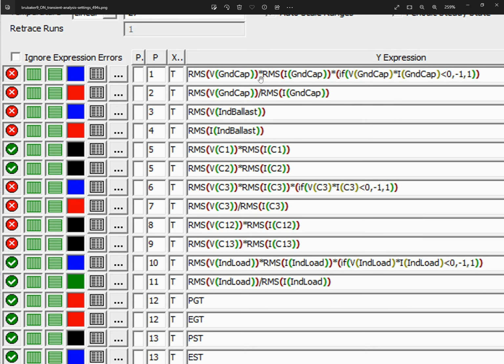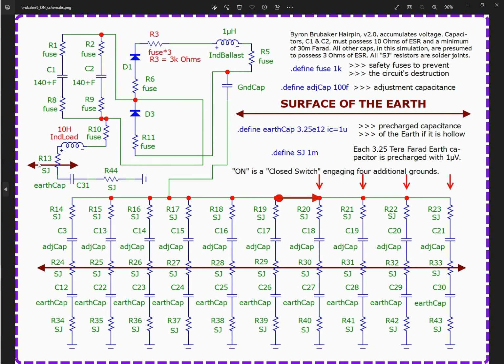Whereas if I have no load on the left-hand side in the schematic, when I have this branch here not connected, and it's just floating, and I only have the ground on the right-hand side here on the DC loop, so there's no ground on the AC side of these diodes, then what happens is the diodes become generators.